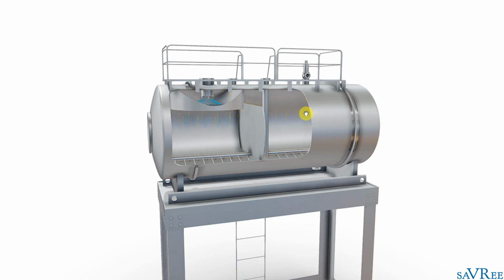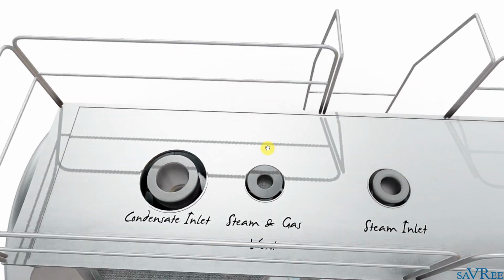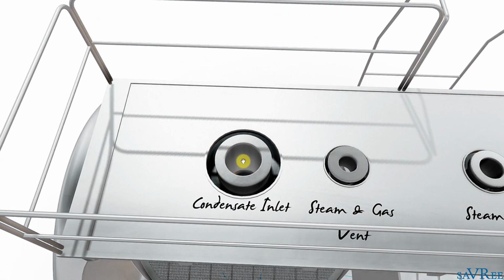The pumps are often centrifugal, so they need liquid in order to be able to pump. They will not pump air. And for this reason, it just makes sense to sit the Deaerator as high up in the power plant as possible. Our condensate is going to enter through this inlet here.